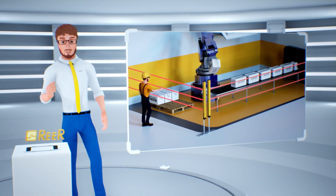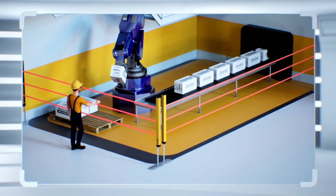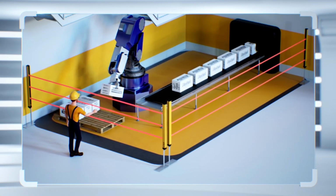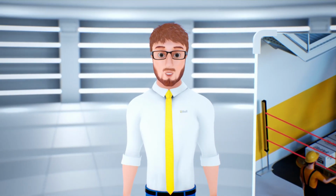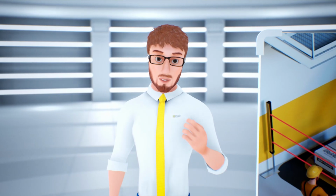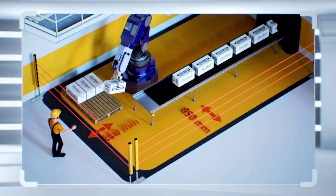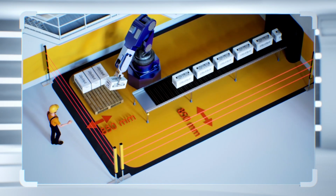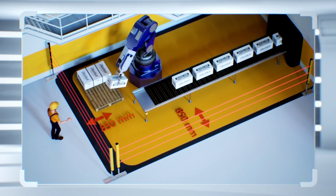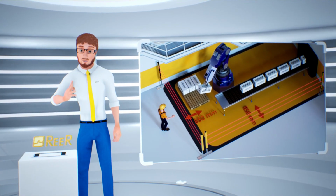On the other hand, if the goal is to detect a person accessing a dangerous area, the ideal type of protection is perimeter guarding on one or more sides of the dangerous area, even over longer distances. These light curtains must be placed at least 850 mm from the dangerous area and normally have a resolution of 2, 3 or 4 beams.